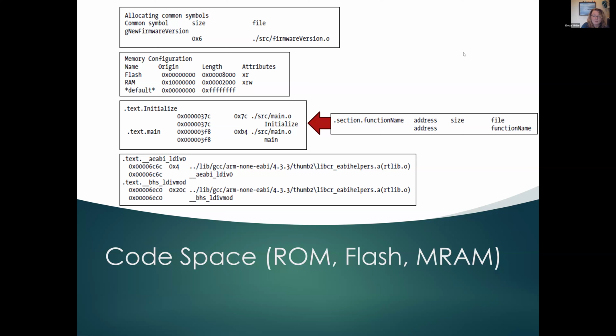256K of code space seems like a perfectly reasonable amount. But then I've worked on projects that had 32K, packing data and algorithms like sardines into a too small can. And when you need to do this type of optimization, when you need to consider what is really happening in RAM and code space, the file to look in is the memory map. The memory map is an output of the build system that says where it actually puts all of the variables and functions that you created.